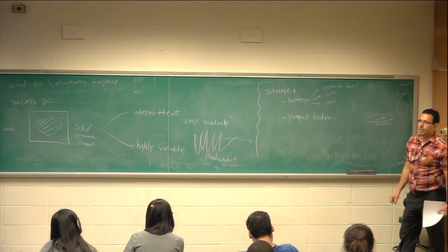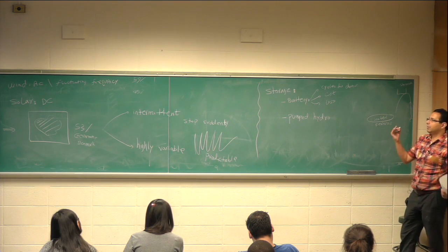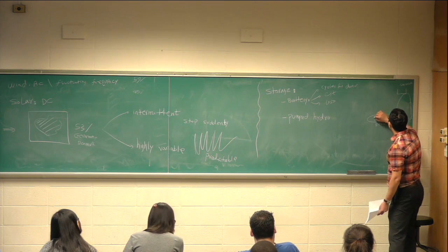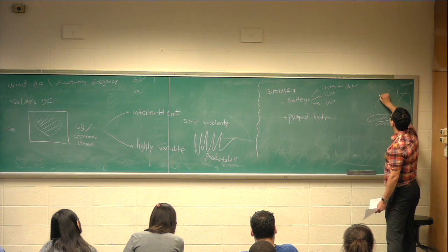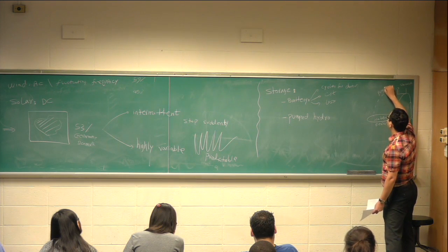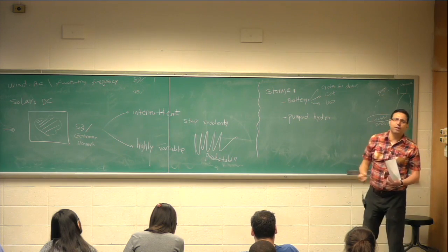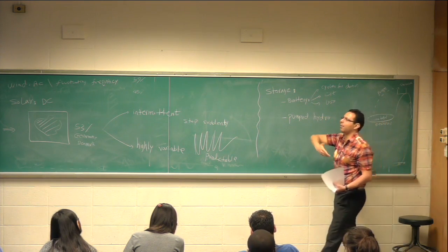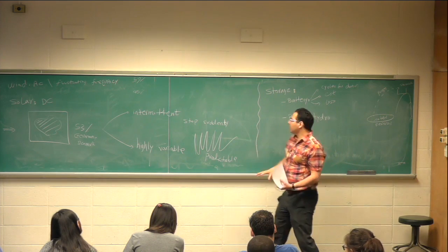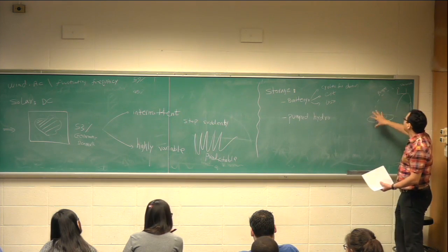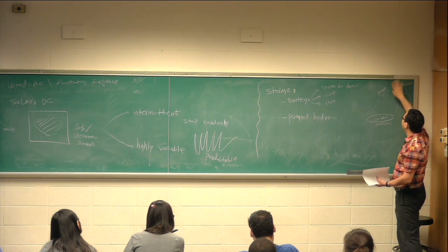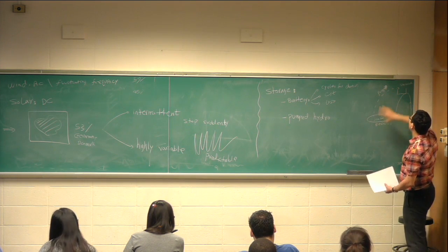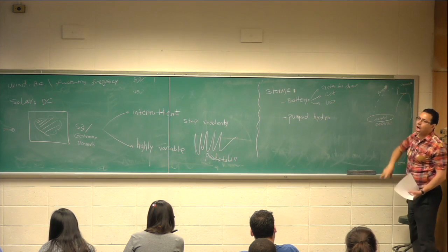What you do is that whenever you have power coming out of wind, you use it to pump water to a higher place. And you don't care about the frequency of wind. It's just for pumping. It's not supposed to be 60 Hertz. It's not supposed to be fixed. As long as you have power, you use that fluctuating power to pump water to a high place, then you store. That's a storage of water.